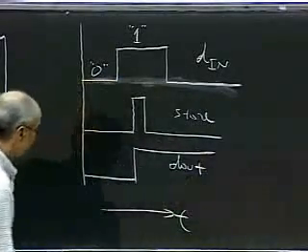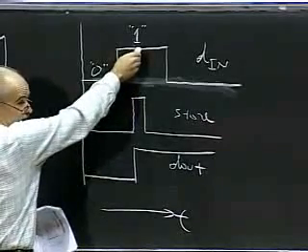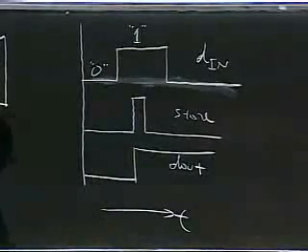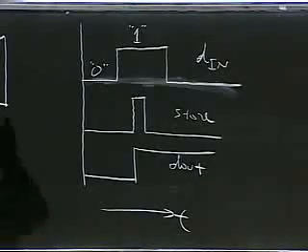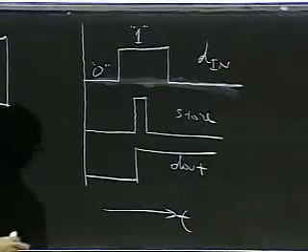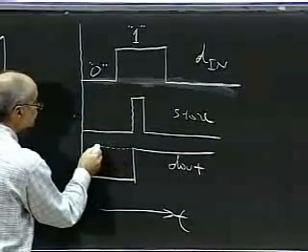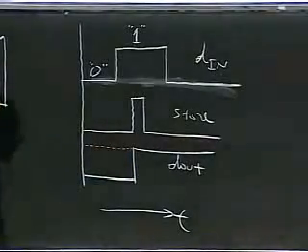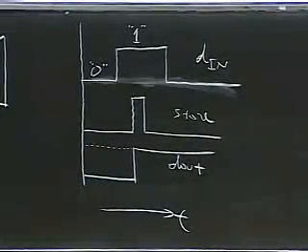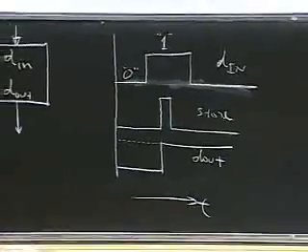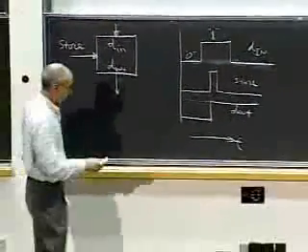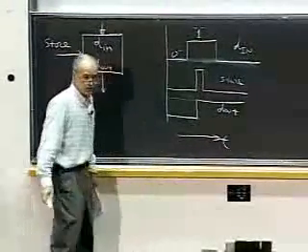So as you can see, it would remember the 1 that it saw at this point. In fact, it would do that irrespective of what was stored in this memory cell. For example, suppose it was storing 1, then the output didn't change. It says, okay, still 1. If we're storing a 0, it will flip to a 1.